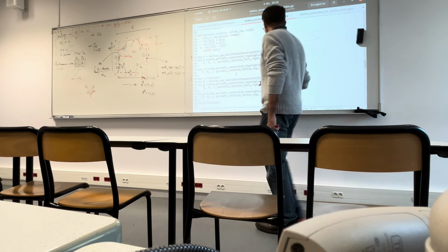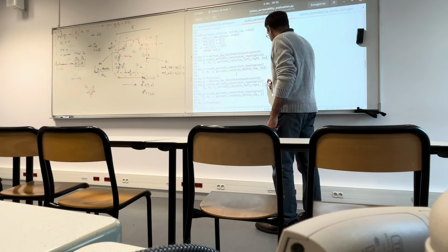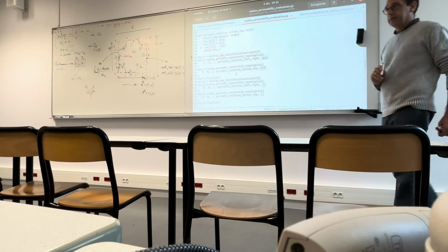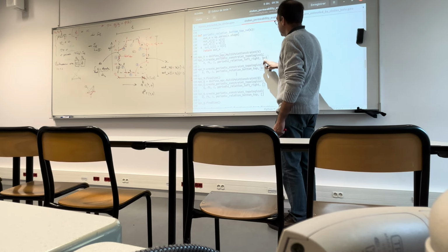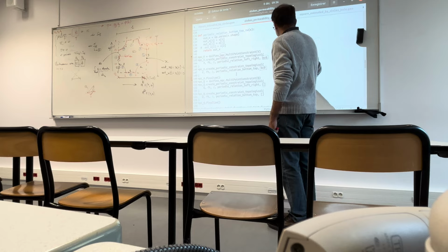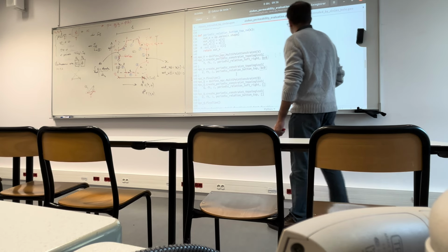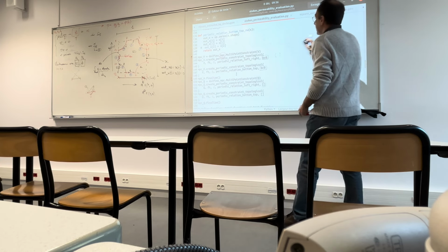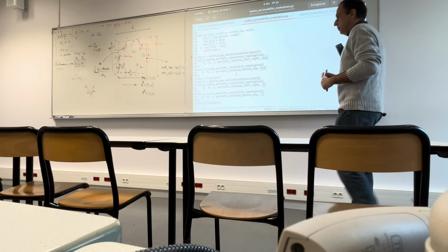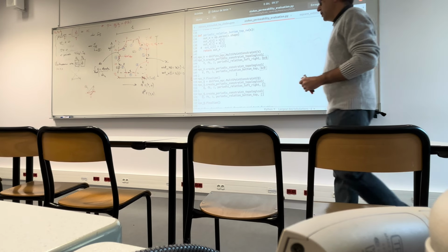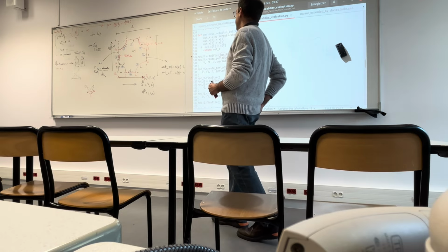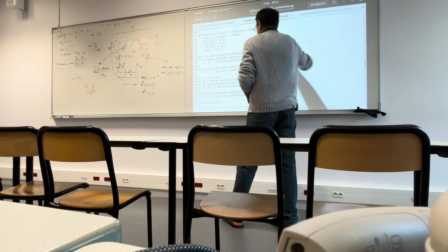For pressure we have nothing, and so we have this empty bracket. Okay. So the boundary conditions that are specified here are within a bracket. So I just put an empty bracket because it looks for something there, but it's just empty. So there are no specific additional boundary conditions for pressure. Okay.